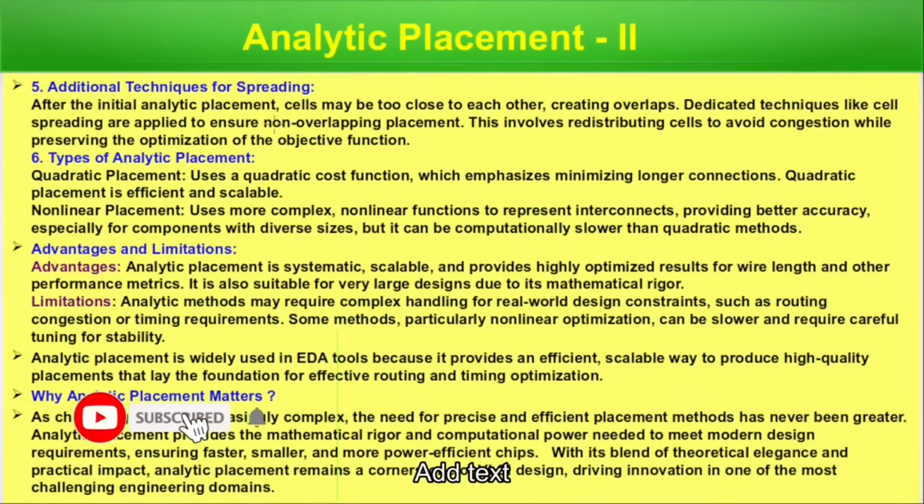So additional techniques for spreading. After initial analytic placement, cells may be too close to each other, creating overlap. Dedicated techniques like cell spreading are applied to ensure non-overlapping placement. This involves redistributing cells to avoid congestion while preserving the optimization of the objective function.